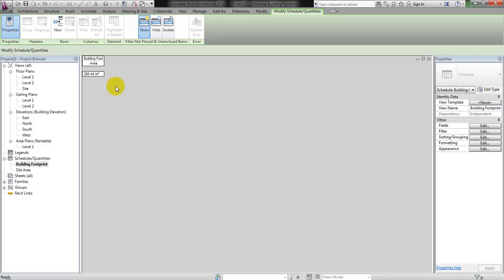I choose this as my main schedule because the building footprint is the one often changed in design, and the site area is always fixed, since once you receive the topographic survey, that is already a fixed area. If there are some changes, I think it's not really much.